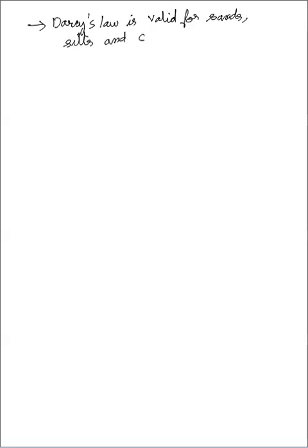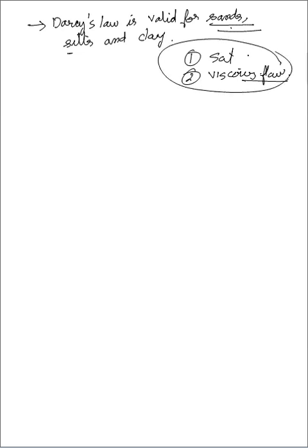Basically it is valid for all types of soil, whether sand, silt or clay, but you have to check all these conditions: the soil should be saturated, and the water flow should be viscous or laminar. These are the main prerequisite conditions, we can say.